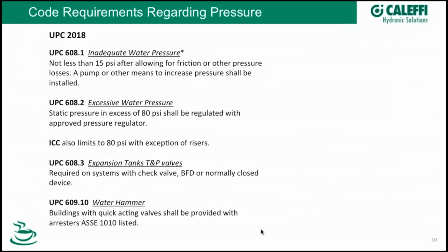All right, here's a little bit more verbiage on the codes. Again, this is the Uniform Plumbing Code, the IAPMO code. They consider inadequate water pressure below 15 pounds. Now, again, if you've got flushometers in the building, that's not going to be adequate pressure to make sure that those seal and shut off tightly. It's probably bad on a urinal or toilet where you flush and it just keeps running and running and running. Sometimes that's an indication that the pressure's dropped too low, where it's not pushing that diaphragm and shut-off mechanism up. And I would say 15 pounds, even in a residential building, would be not much of a shower flow for taking a shower, but that's the number that's out there.